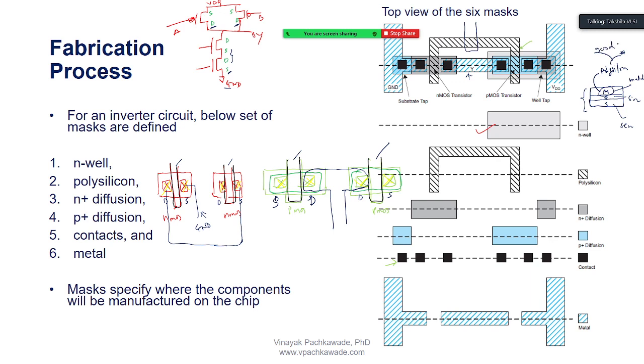So it's same as the metal, and it has some advantages from the technology point of view. That's why they don't use the metal, rather they use polysilicon. So polysilicon acts as nothing but a conductor, no, sir? Yeah, because it is heavily doped. It is a semiconductor with heavy doping, so it is as good as a conductor.